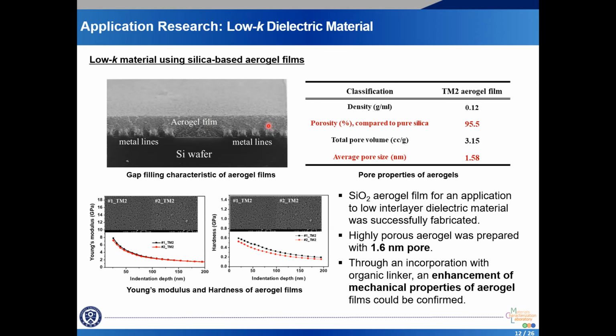In the image at the top, it shows excellent gap filling capability of silica aerogel films. Through incorporation with an organic linker, an enhancement of mechanical properties of aerogel films could be confirmed by nano-indentation measurement, such as around 2 gigapascal of Young's modulus.